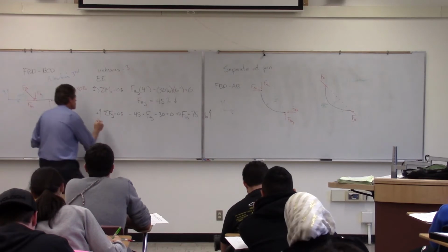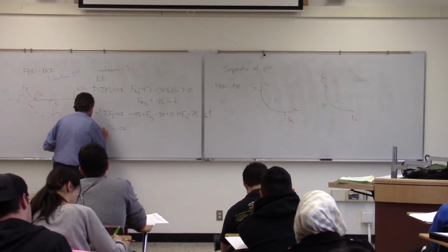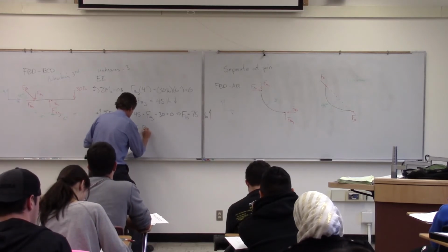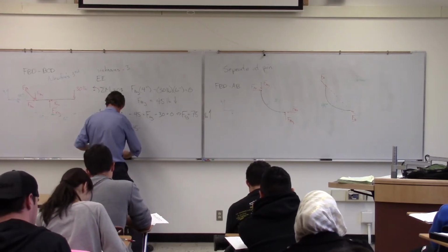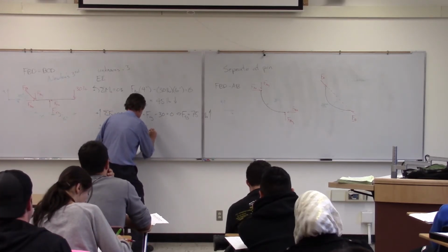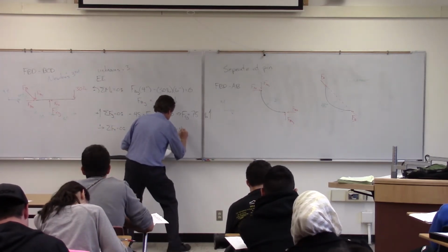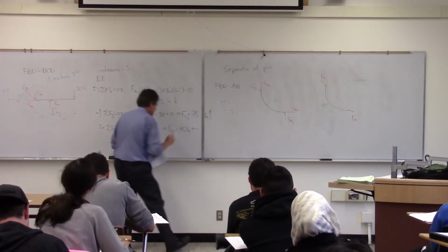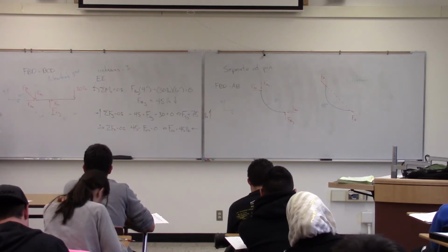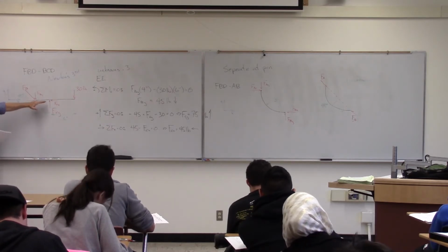And then my next equation is going to be the sum of forces in the x direction. Now I'll get the arrow going in the right direction. And then noting the fact that I know my Bx and By components are equal, since it's a 45-degree angle, my Fbx will be 45 acting in this sense.